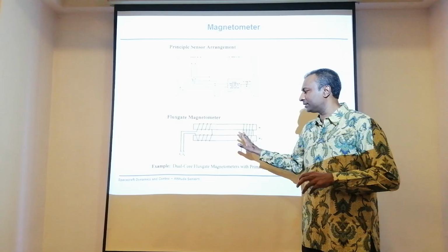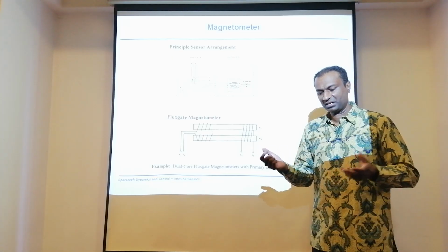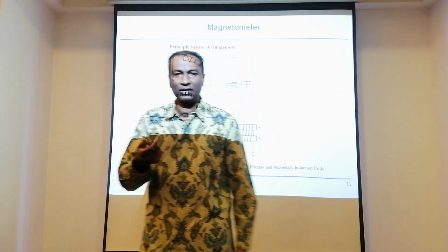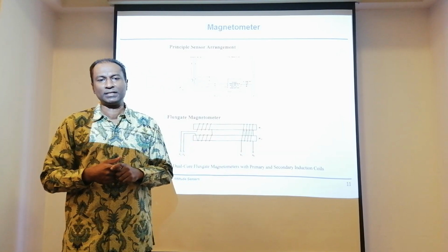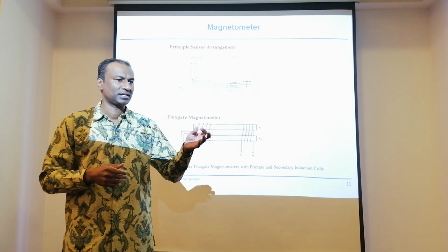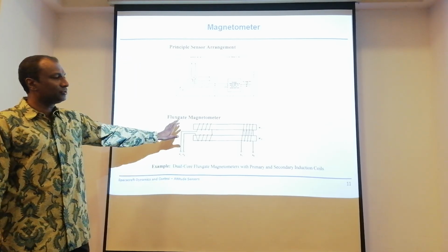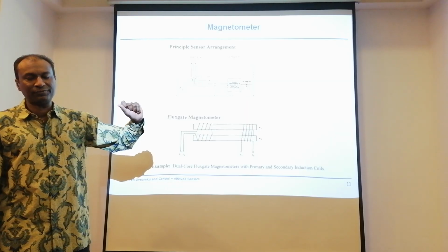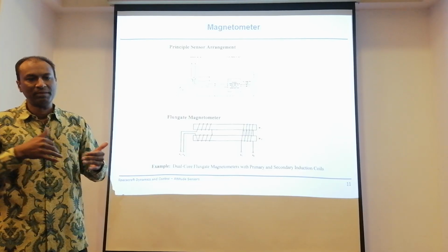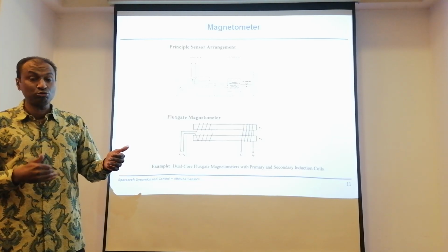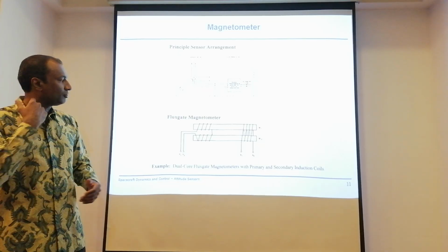Right? It's a very simple sensor. In fact, it's a very small sensor, as good as an IC nowadays. I think in our satellite lab we have done that in our lab exercises. It can be just an IC, and that is a magnetometer. All right. Again, don't expect good or high accuracy from magnetometers, not because of the sensor itself, but because of the estimation that we want to do. The estimation is what is going to produce the lesser accuracy in terms of attitude.